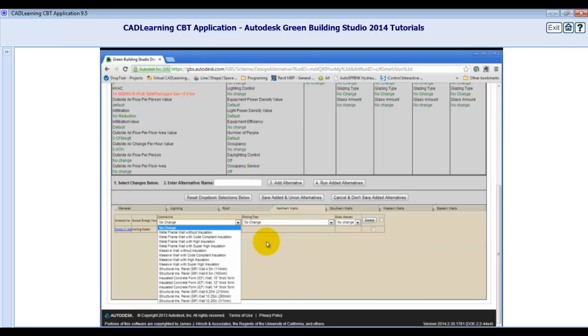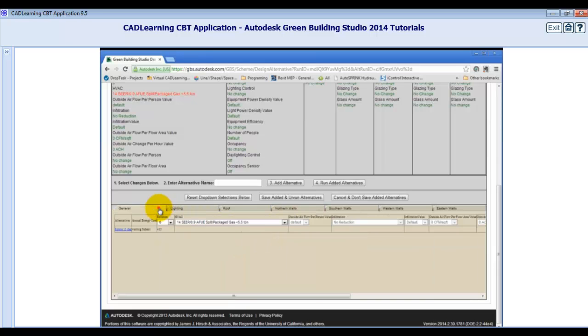Generally, I recommend changing one element at a time. Be aware that whatever you change will affect several calculations. For instance, return to the General tab. Here, if we were to change the building rotation relative to the baseline, it will not only affect the heating and cooling, but also the lighting energy usage, photovoltaic generation, and the potential for natural ventilation.